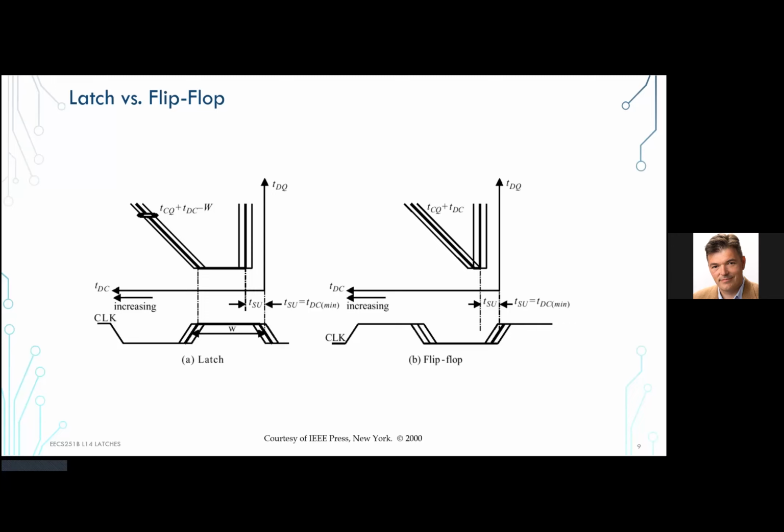If we are arriving to a non-transparent latch, we are adding linearly to our latch overhead. And if you're arriving to a transparent latch, then there is no overhead of that. And then finally, if it has to be relaunched, this essentially corresponds to a failure of missing the setup time on the latch.